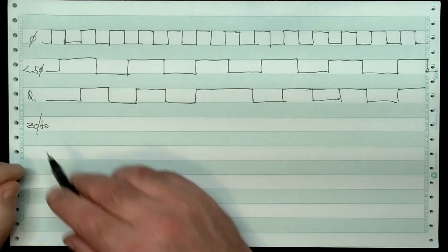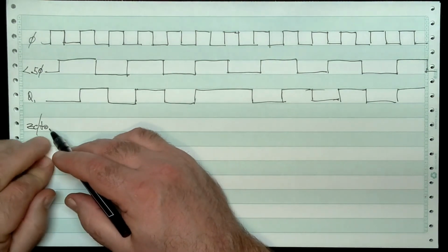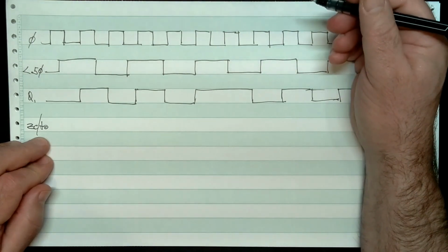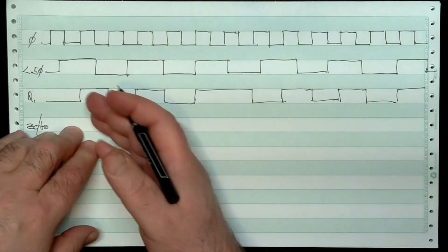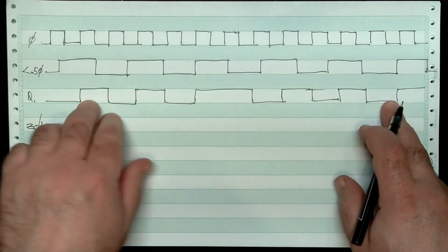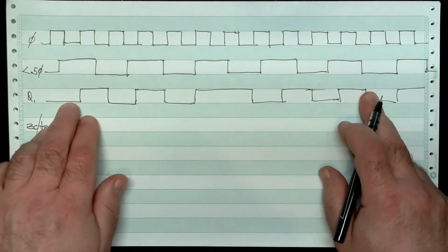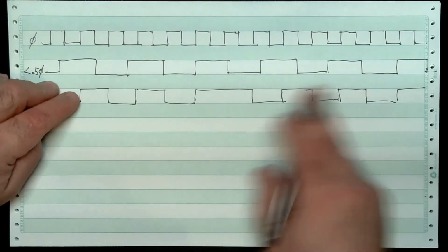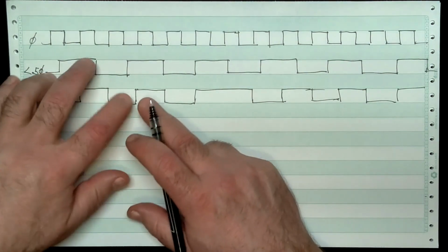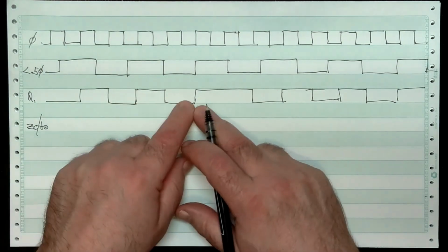so every time this thing pulses is when the main counter will reach 0. Okay. Now we don't know what the counter is. I didn't label it in here, but it will count at the rate that we see based on Q1 here when we're in counter mode. In other words, every time there's a leading edge here, the down counter will tick 1 down, right? So it'll tick there, it'll tick there, it'll tick here, and so on.